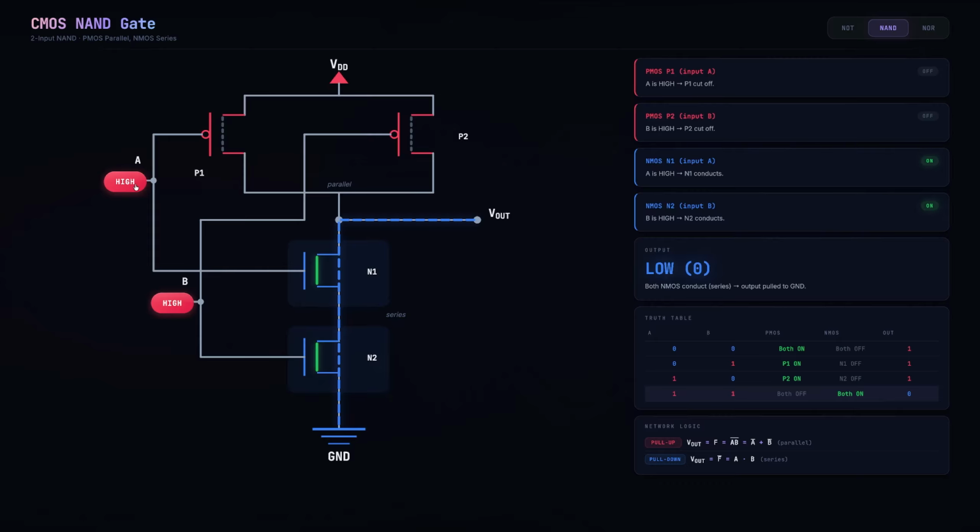Okay, so play around with this. You can see the transistors turning on. When I turn this on, that gives us a path for a connection to VDD. When I turn it off and both of these are high, you have the connection back to ground. When you trace through all the combinations, this gives you the NAND function.